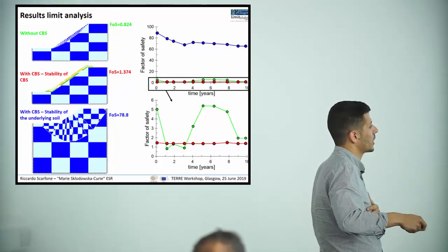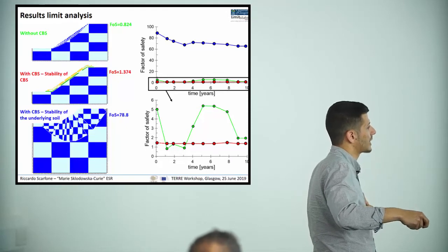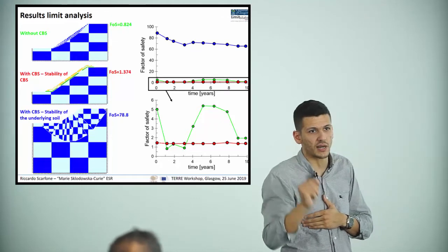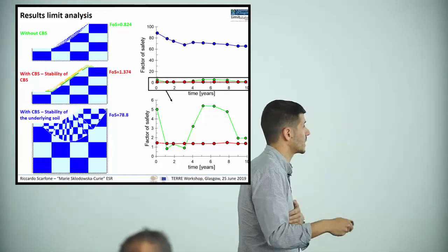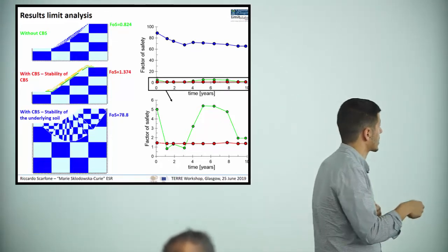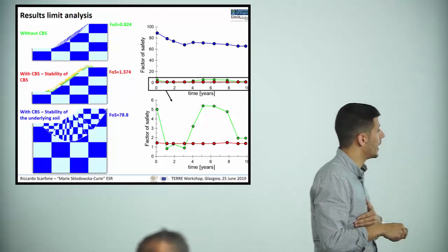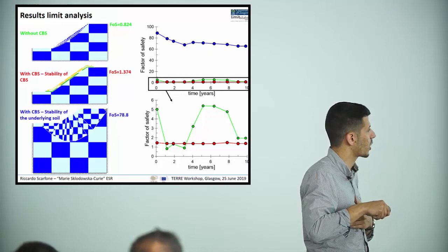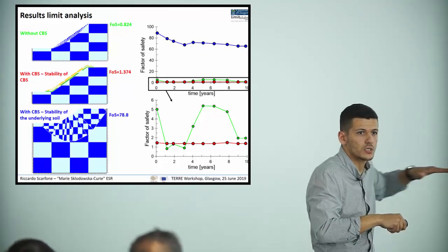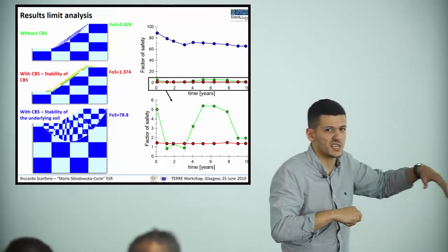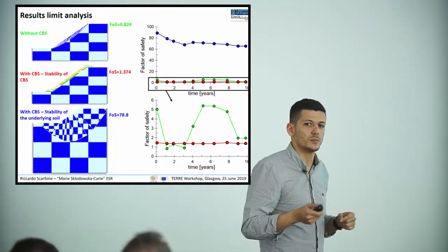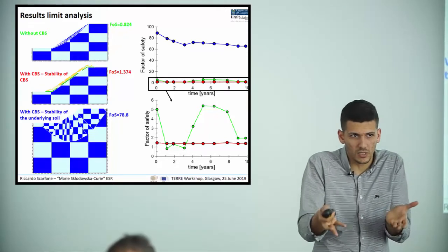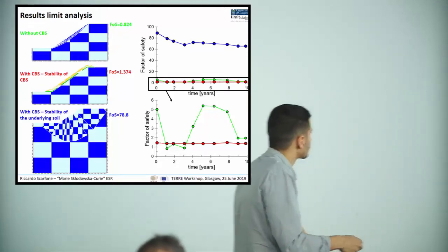Here, same story, we are now plotting the time history of the factor of safety for the wettest critical event of every year, where we can see a similar picture to the one I described here, and in particular you can see the stability of the barrier is more or less constant during these critical events, which means that the stability of the barrier doesn't really rely on suction, but just on the material strength itself.